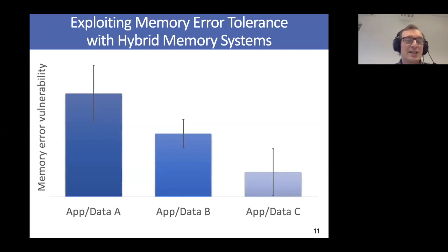It could be something that's really important for the application, like a linked list traversal that really determines what happens afterwards. So it could be important. Whereas for this other data, if you inject bit flips into it, you don't get much of a problem. The application doesn't crash, certainly, and in the end, maybe just a pixel changes on the screen, and maybe no one recognizes that. So I gave you an application that's tolerant.